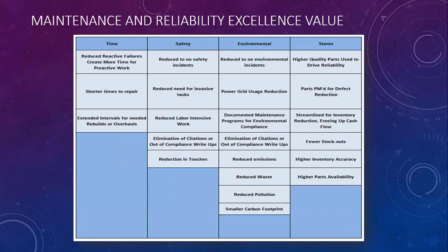Most of it is bearing trending that we're using in pumps, checking for cavitation. So example is our ammonia compressors, we're trending on all the bearings on ammonia compressors, on all of our oven blowers, on condenser tower units, and on hydraulic power packs. And then we check pumps regularly for cavitation. That's a random thing that we're doing because we're seeing an issue. We don't do it as a trend, but just trying to drive a problem out of the system. Somebody had adjusted a hydraulic valve, and we were able to find that and get that system corrected.